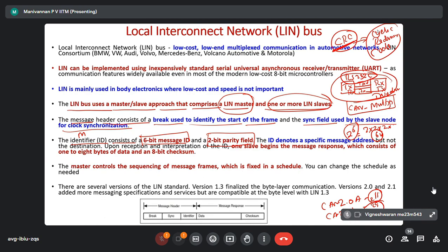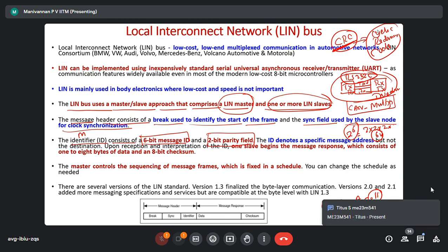Okay, so you know that you have to add all the data bits byte by byte, 4 bytes, correct, with the carry. Finally, you get a sum that should be inverted, bit by bit inverted, the one's complement. Correct. That is what is called the checksum. That will be transmitted along with the start frame, identifier, then data length, RTR bit, then actual data, followed by CRC, right, and other bits and the stop bit, that frame, right.